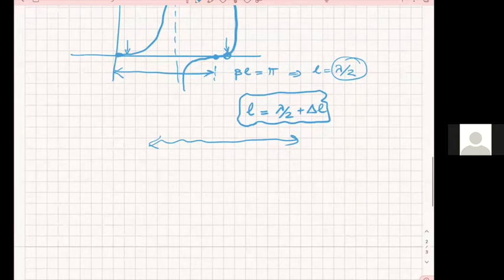The other thing is to look into the capacitance. Now, your capacitance is still a big problem because with your capacitance, you have to bring the ground very close. So here is what I would do. Let's think that both my inductance and my capacitance are very small. So instead of using sections of transmission line, which is also another way of doing the inductance, what if I do lumped elements, what we call?